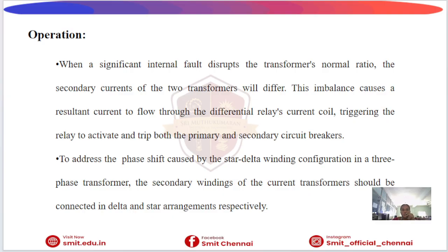Operation of a differential scheme: when an internal fault occurs, the currents become unequal. This creates a differential current in the relay. The relay operates and sends a trip signal to the circuit breakers. The circuit breakers disconnect the transformer. So, we have to protect the transformers.